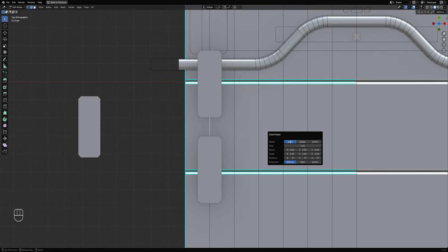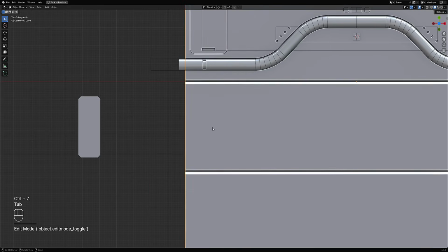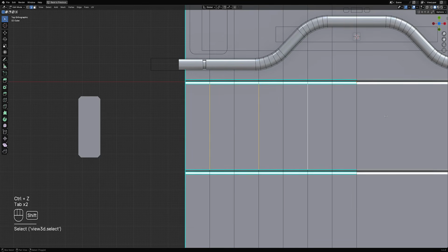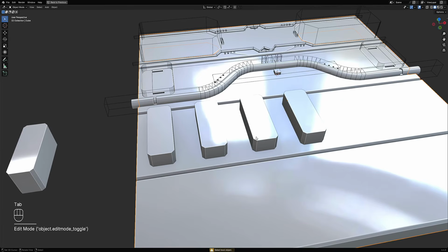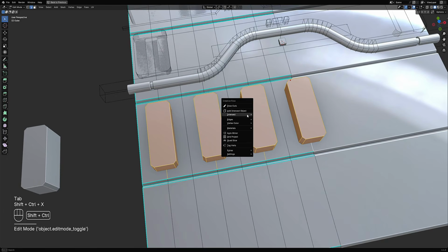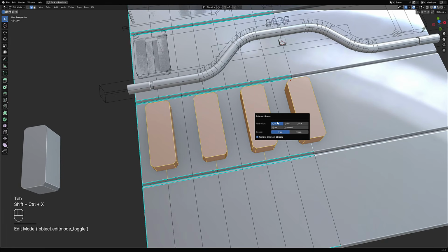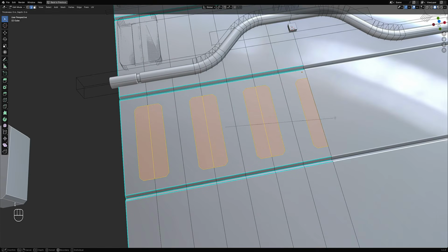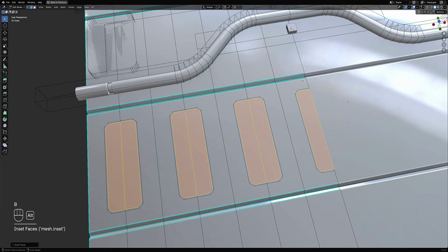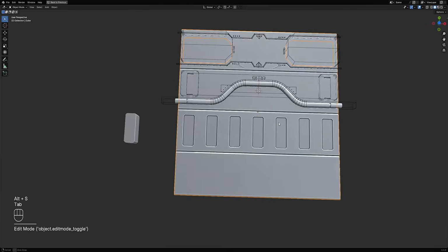So these are positions. So not in the position of verts, but the edges. Got it. Just intersect clone and in the edges, and then selecting our clone faces. Select our work mesh, and then intersect faces, draw. Then we can just inset, press B to avoid the faces in the symmetry line. Do that.